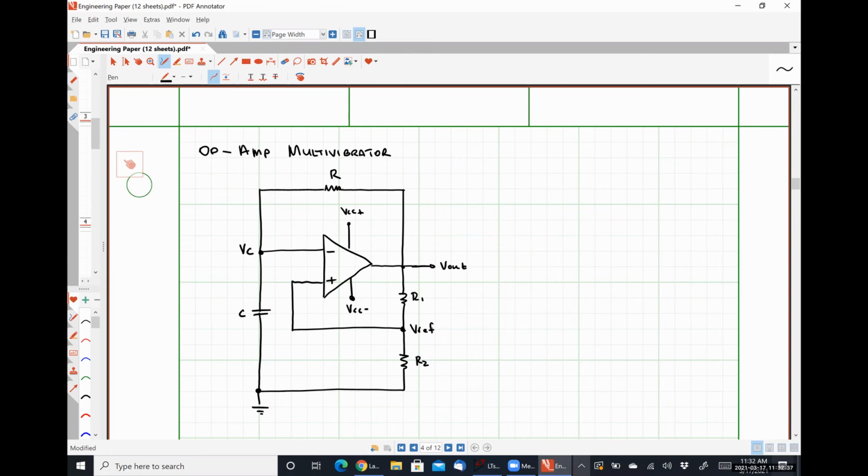Anybody recognize what that is? There's a capacitor. Okay, sure, that's one fundamental difference. Two feedback loops. All right, there is positive feedback through resistor R1 and negative feedback through resistor R. But there's one other thing that's obvious, but you're missing it. Yes, sir. There is no input voltage. Exactly right. There is no input voltage at all. What this guy does is it uses the energy stored in the capacitor to create an oscillating output voltage waveform.